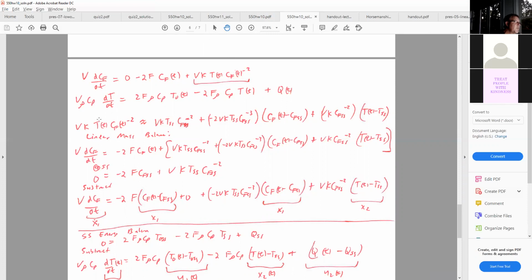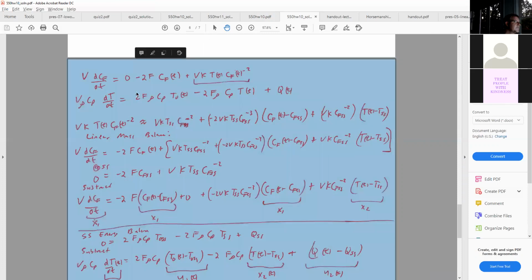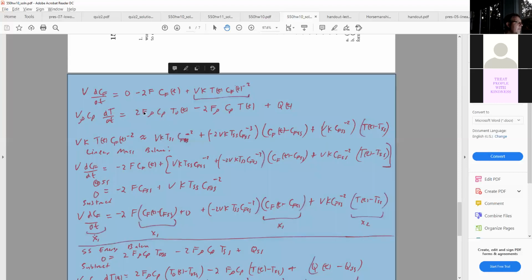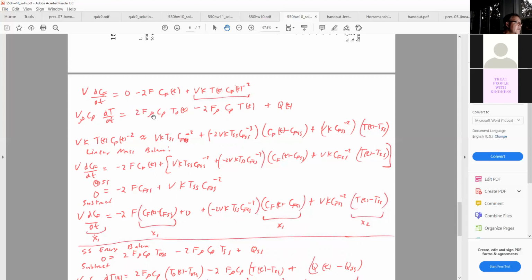We're doing an energy balance as well, so we can track the temperatures. We know the flow rate times density gives me mass per time. Volume per time times density gives me mass per time. The units on CP are joules per kilogram degree. So when we multiply mass times CP times delta T, we get joules.